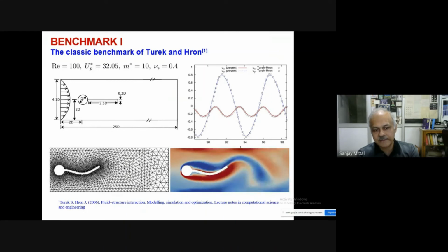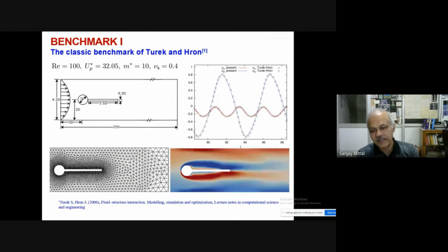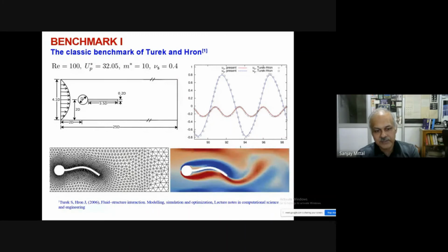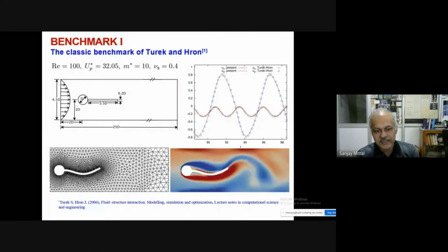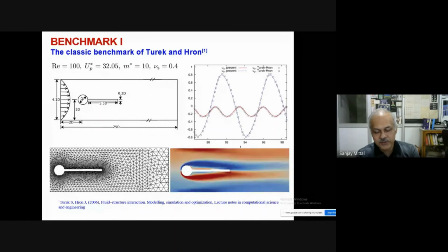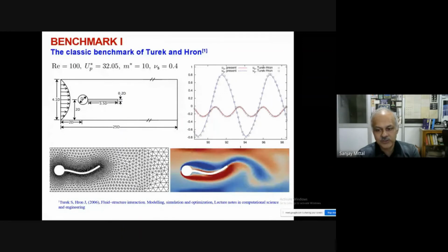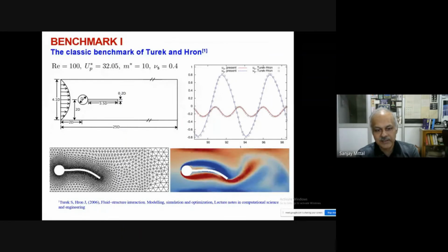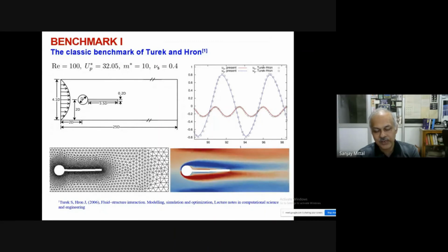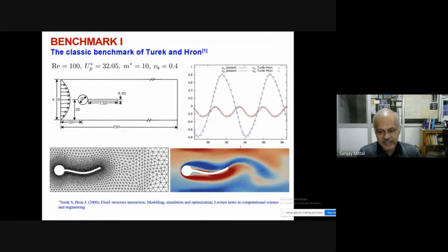So we are not using the lattice Boltzmann kind of method or immersed boundary methods. This is actually a mesh that follows the body. So here, this monkey on your back really disturbs you, how to generate a mesh with these large deformations, and it should not break down. So there are sometimes this motion can become so large and so complex that mesh generation would be the driving constraint in running these simulations.